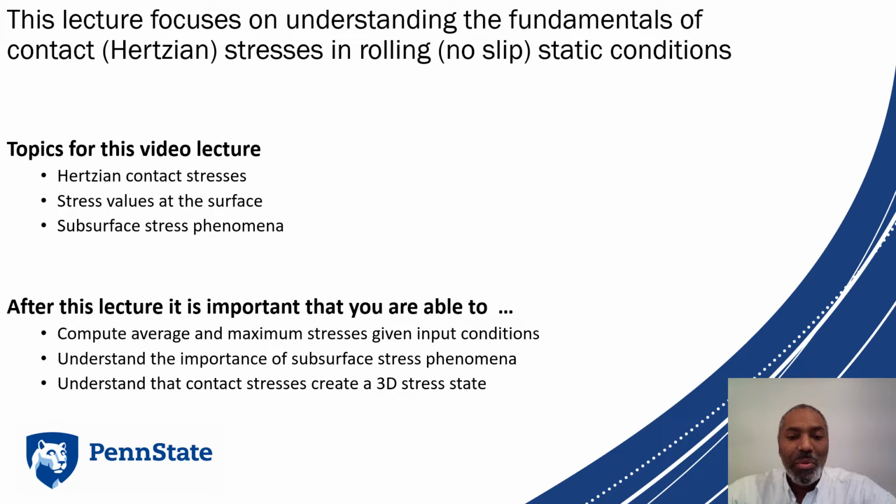Also, to understand the importance of subsurface stress phenomena and how that can lead to surface evident failures, and to understand that contact stresses create a three-dimensional stress state. So yes, we have one body pushing down against another. It seems like it's one-dimensional, but the stress state that it creates is actually 3D.